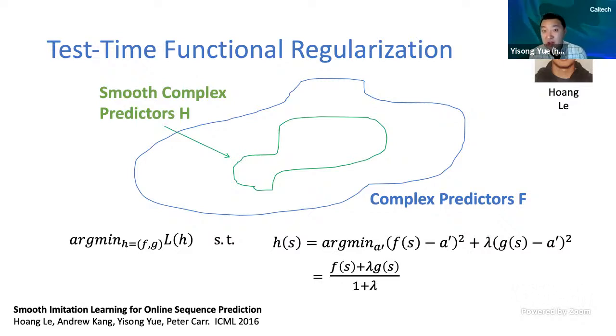What's in the state is where the camera was pointed at the previous time step, two time steps ago, three, four time steps ago. If the state includes all that information, you can measure smoothness using discrete time derivative estimates: the velocity, the acceleration, the change in acceleration. Then you can say, I will never take an action that causes a change in velocity of more than some number, and that's how you ensure smoothness.